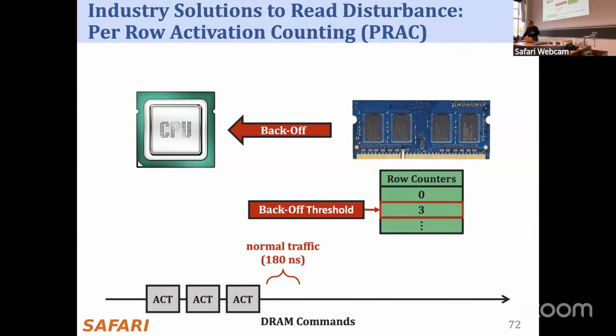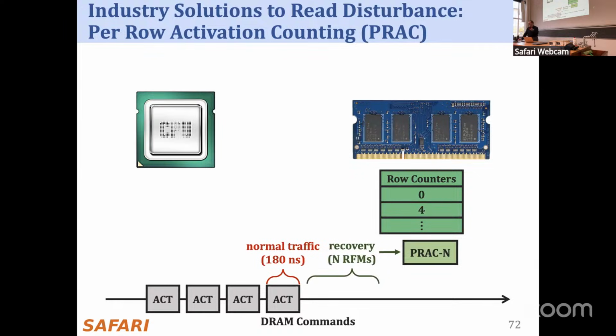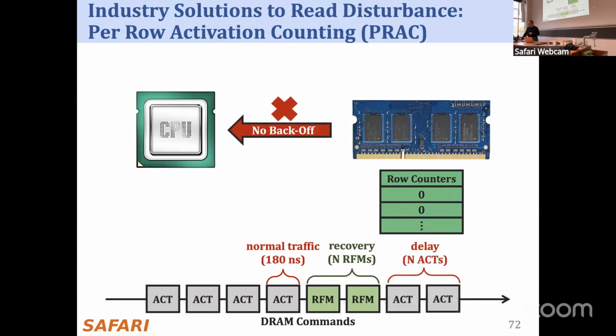At that point, I will not go into a lot of detail because there's a lot of detail over here, but the CPU takes over and essentially sends some RFMs, refresh management commands, to have the DRAM chip refresh itself internally. So it cannot do any other activates at that point. And that interval can be very long, right? Was it 1400 nanoseconds? Yeah, 1400 nanoseconds is a long time. Basically, don't get the DRAM chip overwhelmed.